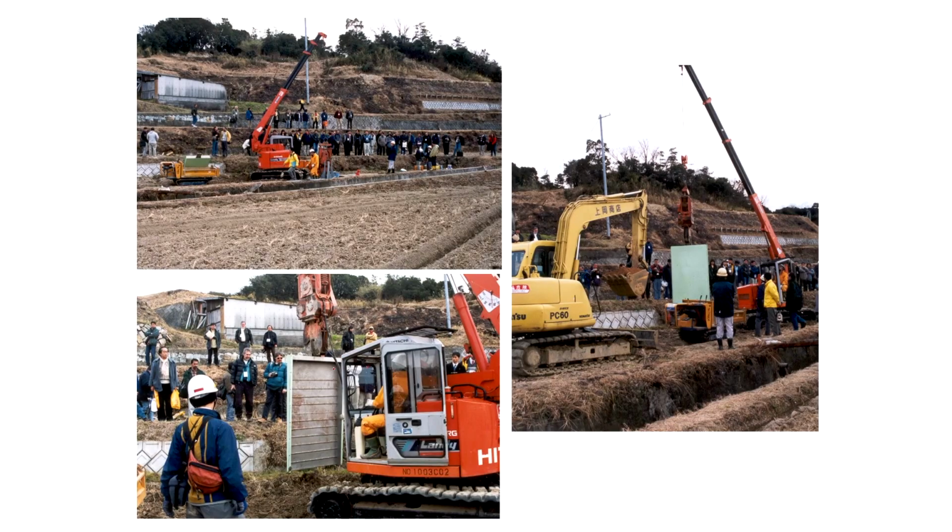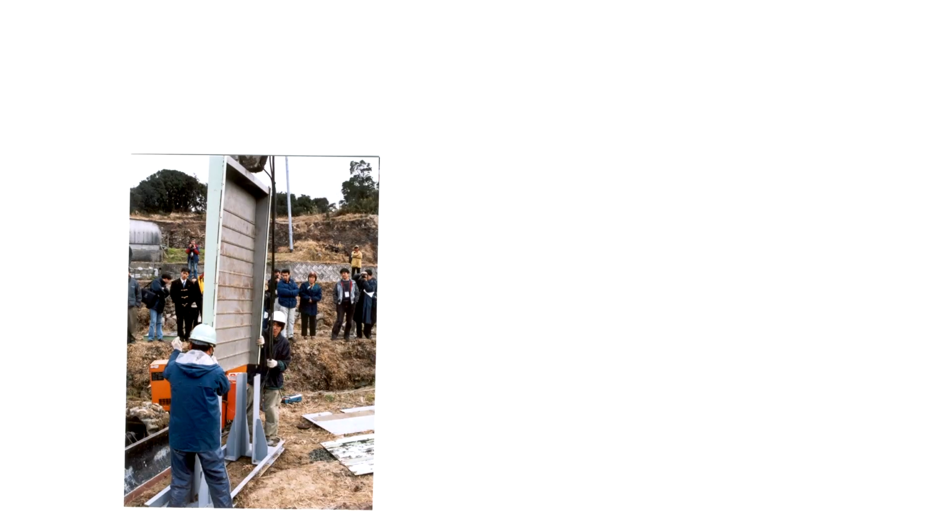But again, there are limitations to this, because geoslicer will not work in the areas where the sediment succession is full of gravels. Okay. So, you will not be able to penetrate with this geoslicer. Okay. So, as I told, this is almost 2 meters by 1 meter, and then you insert this into the ground by hammering it. So, this is what has been done.